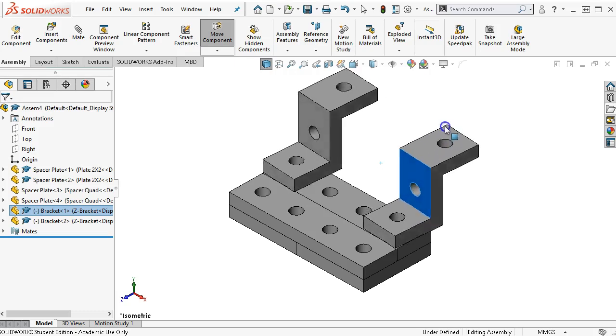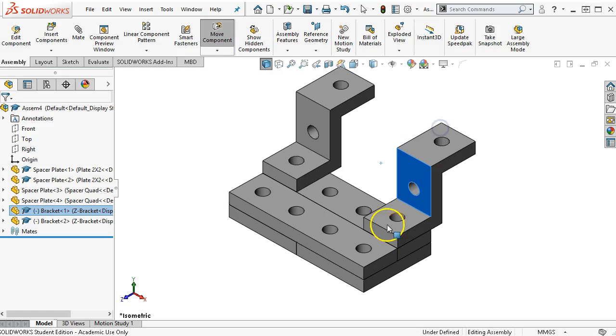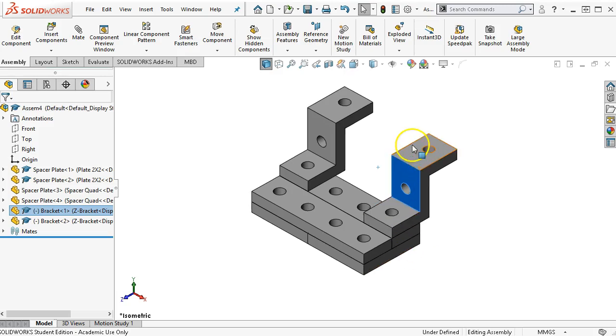Because these are pegged, there is no compression to a fastener, to a threaded nut and bolt type situation that is going to hold these in place. So in theory, we peg all of these together. We have the 10 by 20, we have a 10 by 30, and these guys are going to be able to rotate.